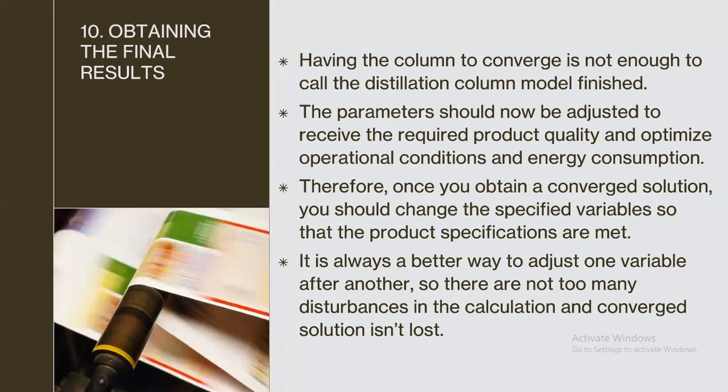It is always better to adjust one variable after another, so there are not too many disturbances in the calculation and the converged solution isn't lost, right? If you try to change many things, your convergence might be lost, and you get into trouble.